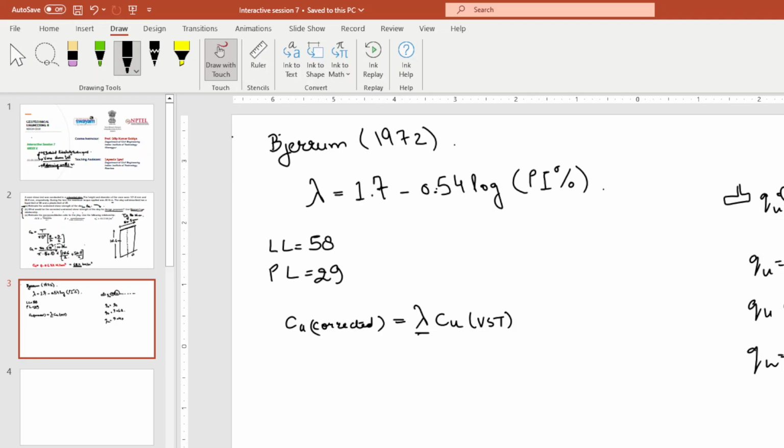So if you provide a high Cu, you will get a high bearing capacity, high final load. So as a designer, I may propose that this footing will withstand 1000 kilonewton when actually it won't. So to be on the safer side, to be conservative, I will reduce this a little bit and then give my design, because even if it is overloaded a bit, it will not fail. It's kind of a factor of safety. Do you understand? Okay. So calculate this.